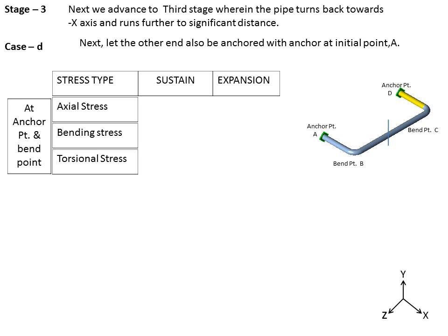So herein again we don't have any axial stresses. Bending stress is reduced significantly because now instead of a support we are having the two fixed anchor points, which is not allowing the system to bend out of plane easily as it was the case earlier where a simple support was provided, or the first case 3A wherein no support was provided. So bending stresses over here, because of the anchor points at both ends, get reduced, and the same is the case for the torsional stresses.